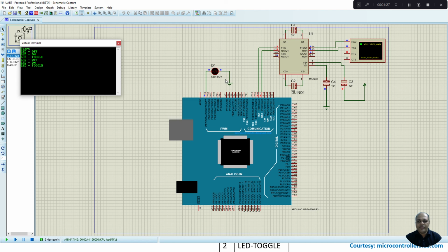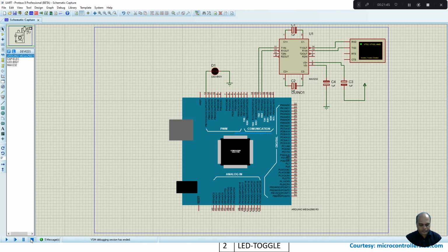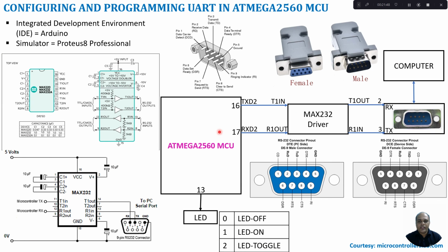With the help of this UART communication, we can send data to a GSM module. We can get the data from a GPS module. Whichever device works with the UART protocol, the data transmission and reception can happen using this mode of communication. So in this tutorial, I have discussed how to use the UART protocol for data transmission and reception between 2 devices, and why we need to use a MAX232 IC for the communication purpose.